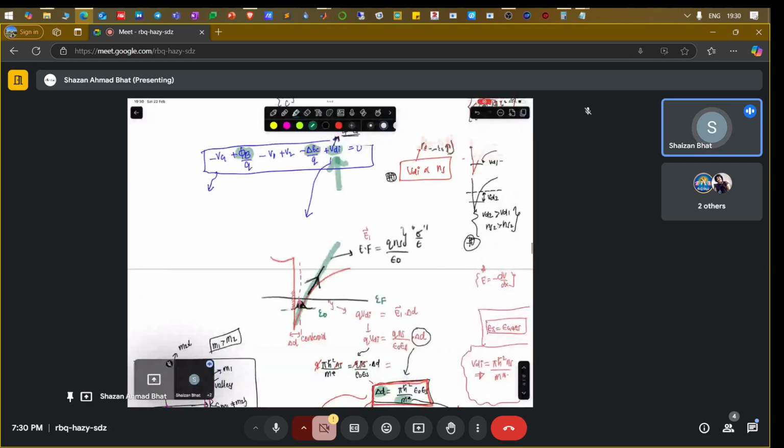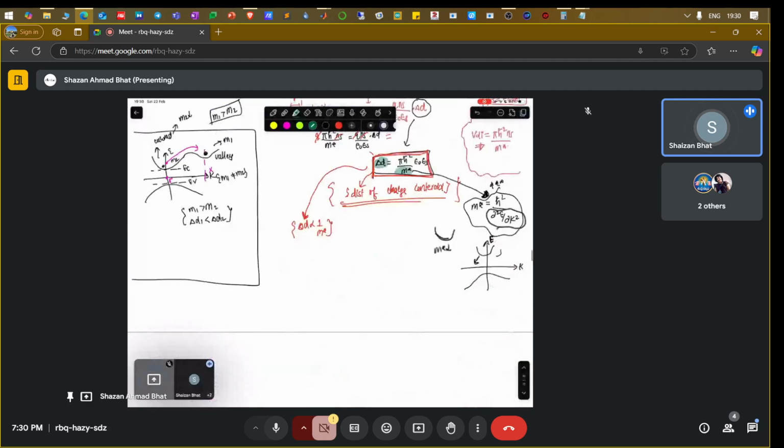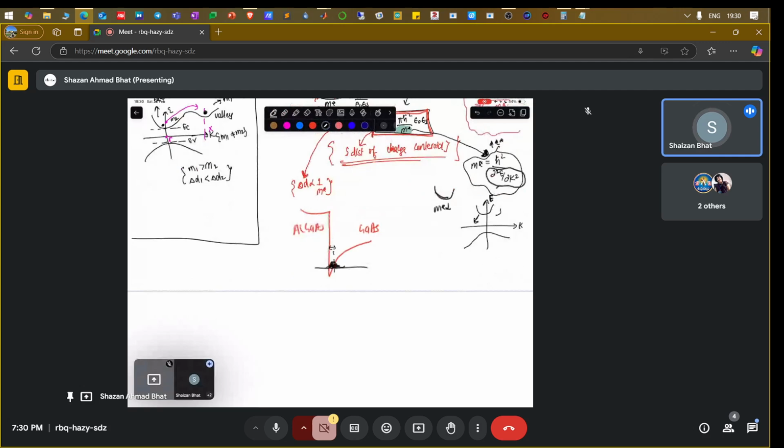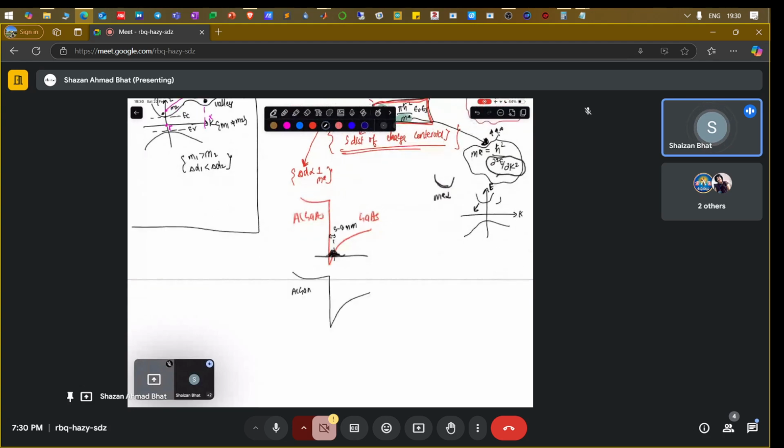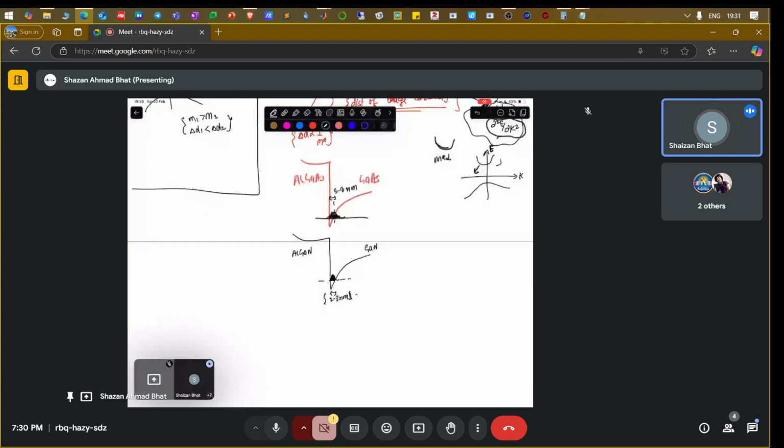Okay, we have computed the distance and the typical values. If you have a AlGaAs/GaAs based HEMT structure, and you have this as the centroid, then this particular distance is typically 5 to 8 nanometers in gallium arsenide. But if you have an AlGaN/GaN based structure, aluminum gallium nitride and gallium nitride, then this particular centroid distance is 2 to 3 nanometers in GaN/AlGaN based heterostructures. Okay, so that is just a little more detail about it.